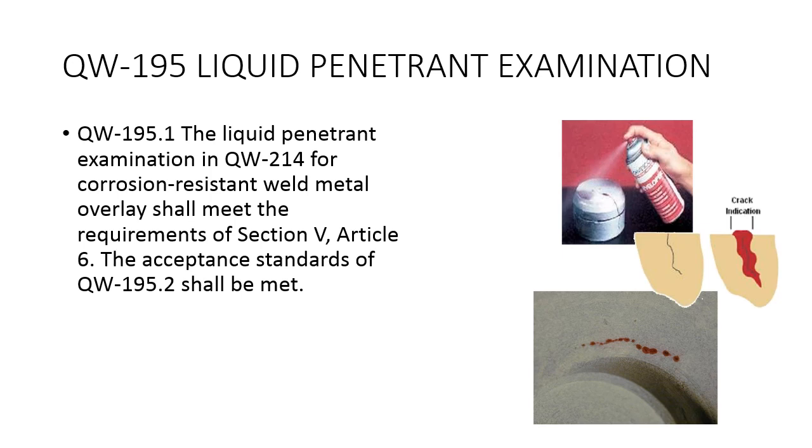Liquid penetrant examination, you spray a dye on a part. You let it dwell for a bit. You spray on some developer. That's after you've wiped off the excess dye, and then that's going to draw out the dye. And if you have any defects or discontinuities, they'll show up on your surface, and then you're going to make a determination on whether or not that piece has passed, if it's met your acceptance criteria.